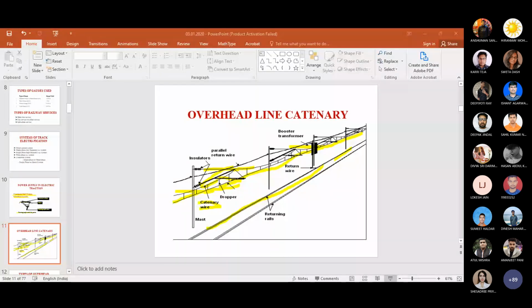So a rheostat is required. How do you counter such a high current? You have to incorporate some resistance in series with your armature winding. That additional resistance, the rheostat, is added. Here you can see the rheostat portion, connected in series with your armature and field winding. So in a DC series motor for traction, the field winding, armature winding, and external resistance are all connected in series.